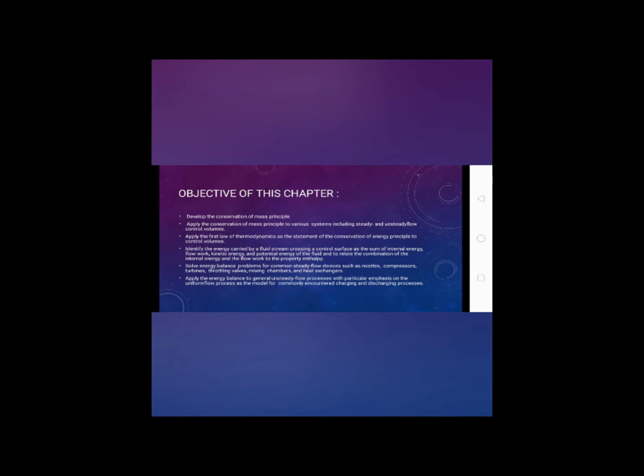Next is to identify the energy carried by a fluid stream crossing a control surface as the sum of internal energy, flow work, kinetic energy, and potential energy of the fluid, and to relate the combination of the internal energy and the flow work to the property enthalpy.